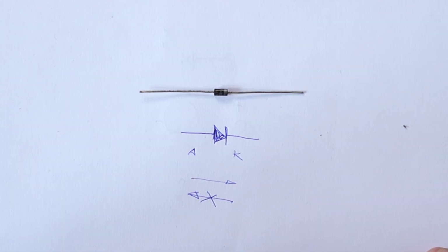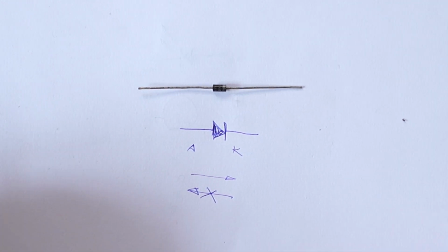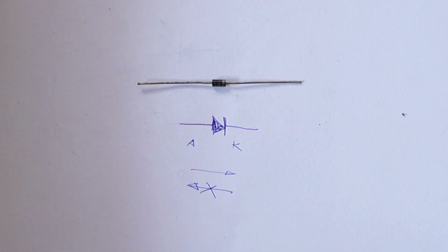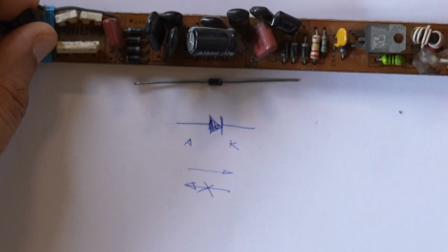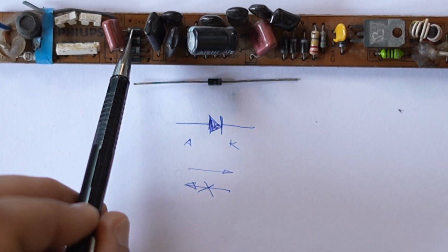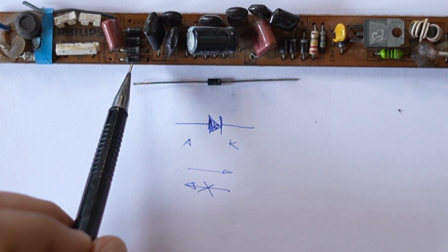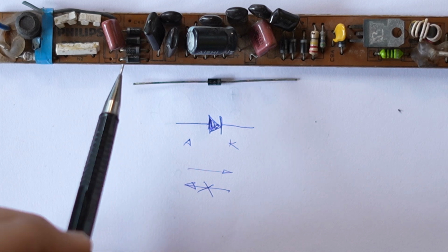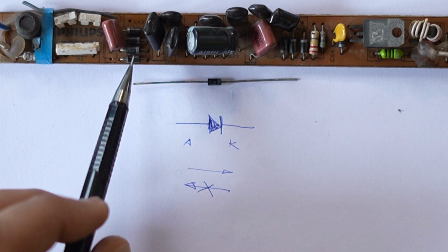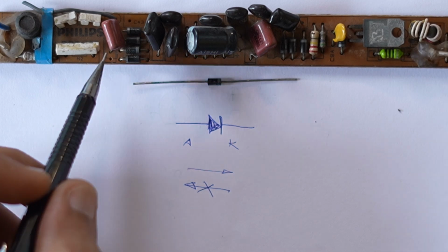So it's used for regulating current, for protecting devices, and a whole bunch of applications. You really find them everywhere in electronics. Let me show you a few. Here's that circuit that we've been taking a look at often, and you'll notice that there's a whole bunch of diodes here. These are 4 diodes, and by looking at it I know that these are forming what's known as a bridge rectifier, where these 4 are connected in a bridge configuration, and they receive alternating voltage as an input,